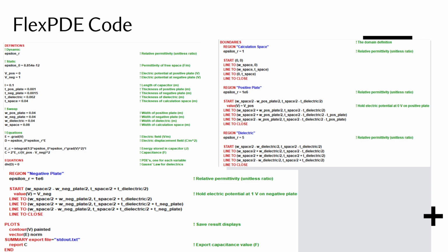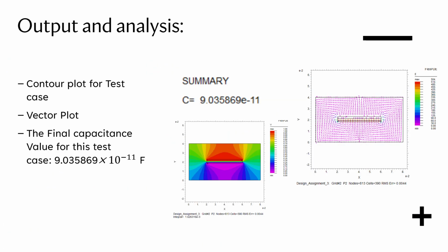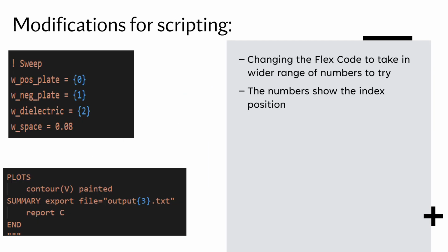The vector plot produced by the simulation illustrates these effects, therefore confirming the accuracy of the model. The contour plot of the voltage distribution in a capacitor with dielectric is consistent with the expectation, showing the voltage dropping throughout the dielectric from the negative to positive plate, and some voltage spreading into the vacuum. The vector plot demonstrates the electric field straight across the dielectric, with highest intensity within it, and lower intensity near the edges of the capacitor. The fringing effect is captured by the model. The electric field appears toroidal outside the capacitor as expected.